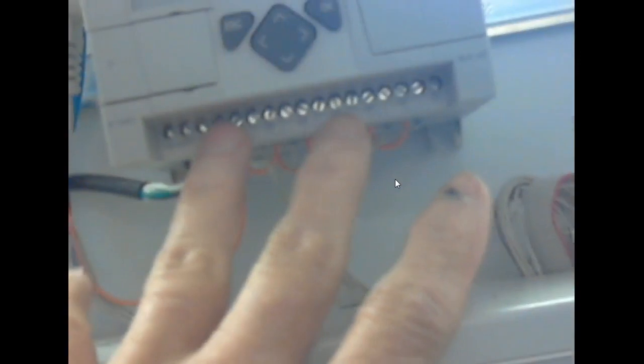So I established a common on these, and notice I've got this guy here jumped all the way down. Here every output port has its own common, and it's a relay output. So relay outputs mean that I can put AC down here, I could put DC down there, and then we would have to look and see what the contacts are rated at. Contacts are rated in two things. What are the two things contacts are rated in?